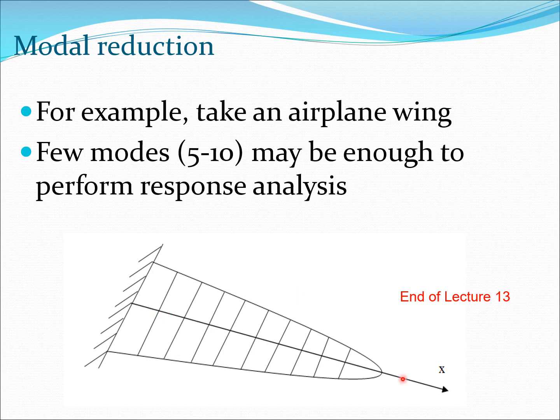So we may take some bending modes, we may take a few torsion modes, and then we are well set with our problem. So this is a huge simplification in structural dynamics, which is widely used in the solution of many response problems and also problems in flutter and divergence and so on. And it really helps the life of people who are dealing with dynamics.